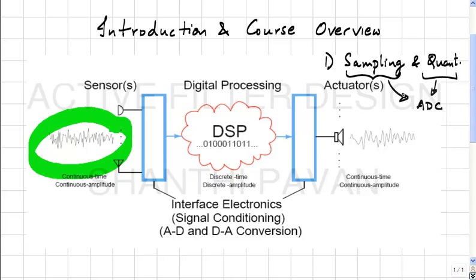So, the golden rule therefore is that before you sample, you must have what is called an anti-aliasing filter. The job of this anti-aliasing filter is to remove all frequency components in the signal beyond at least the 0 to Fs by 2 band, right. Many times, as we have seen in the oversampling case in the data conversion class, the signal bandwidth can be much smaller than the sampling rate, in which case the specs on the filter get greatly relaxed.